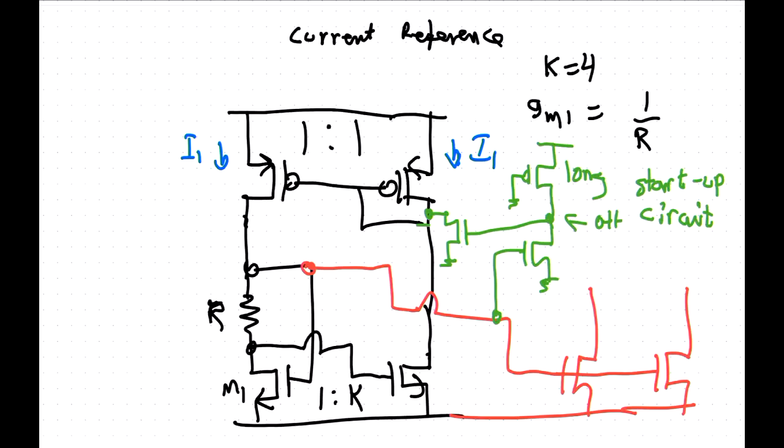Because the gain from here to here is amp squared per hertz. So, you mean that increasing the drain current will reduce the input referred voltage noise? That's your point. Yeah. In an op amp, the input referred voltage noise is normally what matters. But it depends on the circuit, because if your input goes into the source, then you want a lower current, because now this matters.